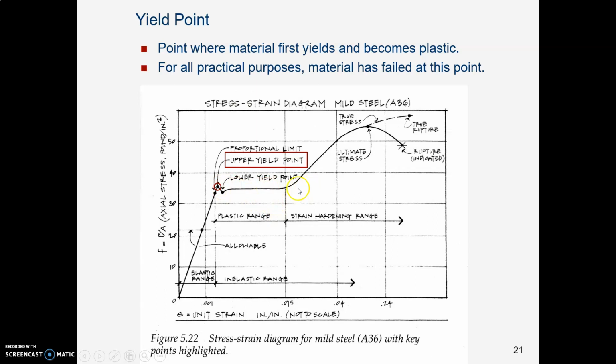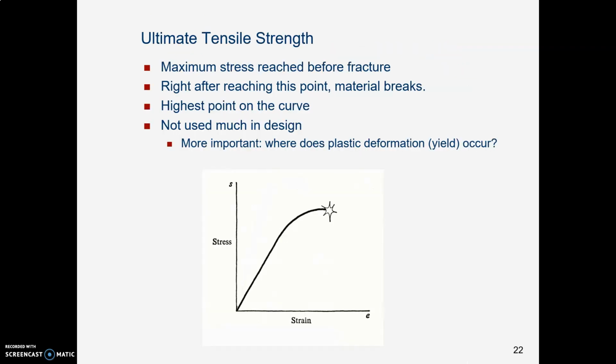What is important about this? It's no longer elastic. It's now plastic. The material has yielded. For all practical purposes, that material has failed. Now, it didn't break, did it? It has not broken into two pieces. It has just stopped being elastic, and it's all stretched out like silly putty, and it's not coming back.